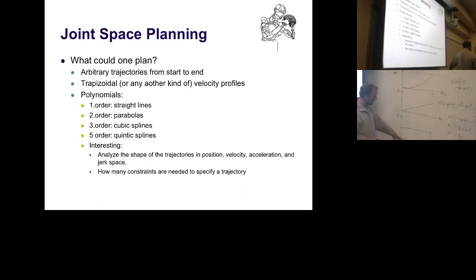Constant acceleration, but you still have a jump here, and these discontinuities are annoying. So that's why people don't like that so much, because if you have a discontinuity in the acceleration, you basically start from 0 and put it up to a value. Again, you get that kind of grinding noise in your robot, which is quite unhappy. So second order polynomial, maybe not the perfect one. Let's do more.